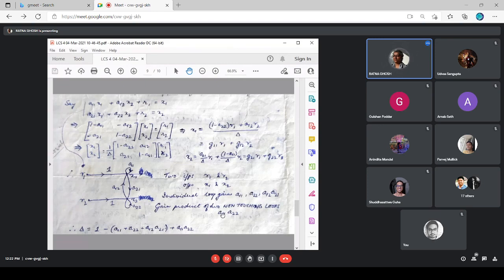These are part of this non-touching loop system, right? Yes, ma'am. So if you compare it with this one now, that's the only other option left. That would give you 3 loops, this, this and this, with these 2 being already non-touching. But this and this, whatever combination you take, there are common nodes. So there are no 3 non-touching loop combinations.